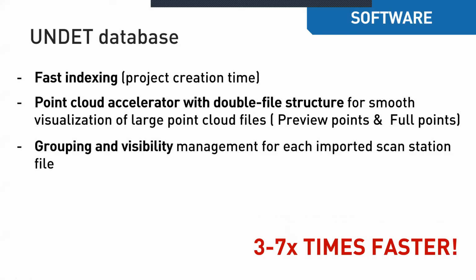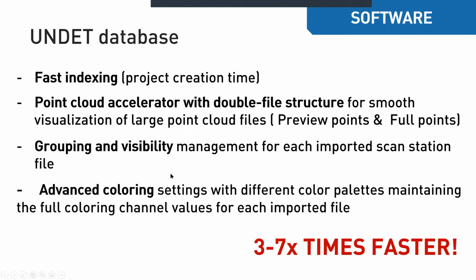And another feature is grouping and visibility. With UNDET and all our solutions, you can group scans into inside and external scans. If you are new to point clouds, it's not a big problem when working with small data sets, but if you are working with larger data sets with inside or external scan stations, sometimes this is missing and you need this function.